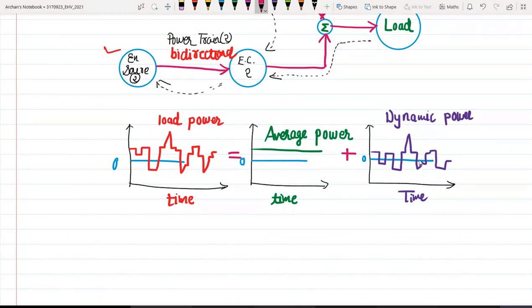Okay, so in hybrid vehicle strategy, one powertrain that favors steady state operation, such as an IC engine or fuel cell, can be used to supply the average power, and on the other hand, other powertrains such as an electric motor can be used to supply the dynamic power. Okay, so the total energy output from the dynamic powertrain will be zero in a whole driving cycle. What does it mean?